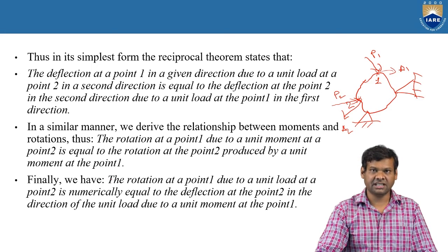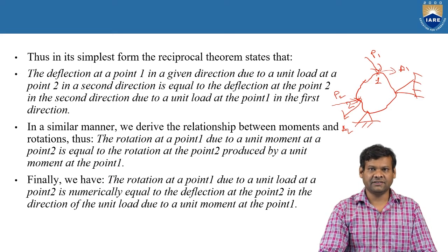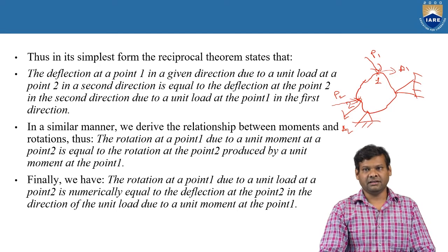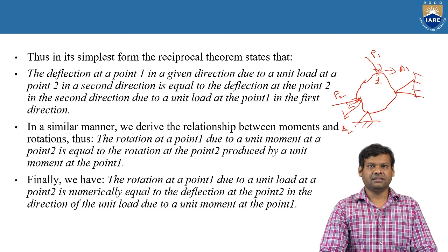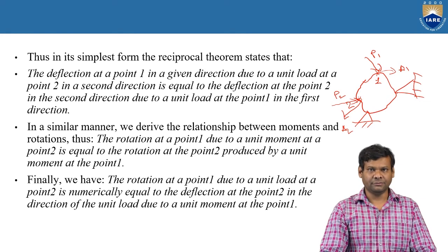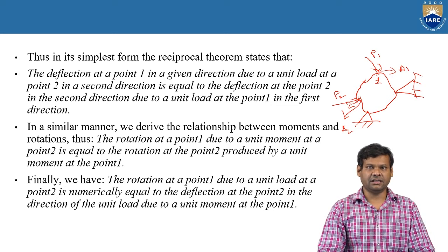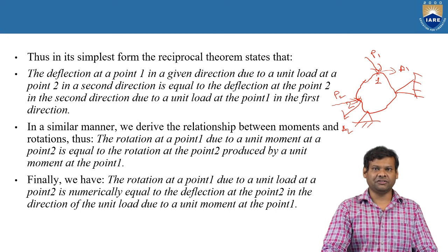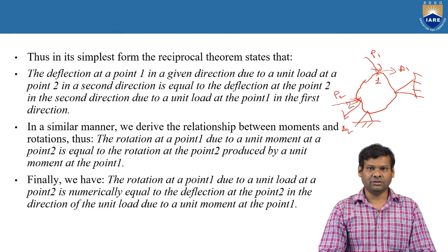Finally, these are the three statements of the Maxwell Reciprocal Theorem. One is defined for the deflection, another for the moments, and another for the rotation. In either case, deflection, rotation or moments, the reciprocal theorem holds good. The most important thing you need to observe is the direction of the load and the direction of the displacement. When you have a clear idea of these two, you can easily find the influence coefficients. Or if you have an influence coefficient matrix, then we can find the deflection if the load is known, or if the deflection is known, we can identify the load.